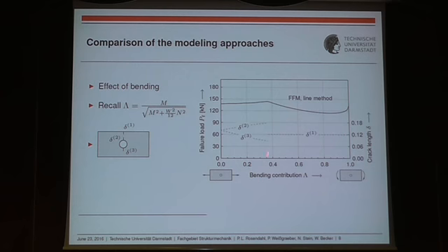Until this point of transition in a critical bending and loading, we observe a sudden transition from the cracks at the hole into a single edge crack, which is associated to a kink in our failure load curve.